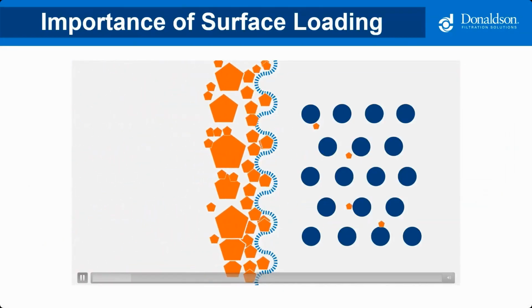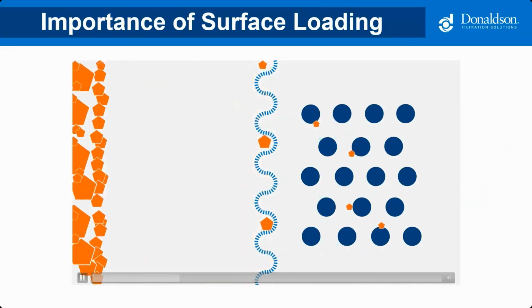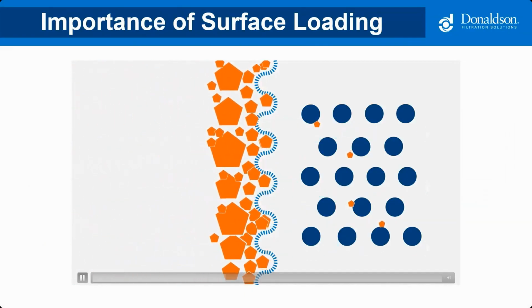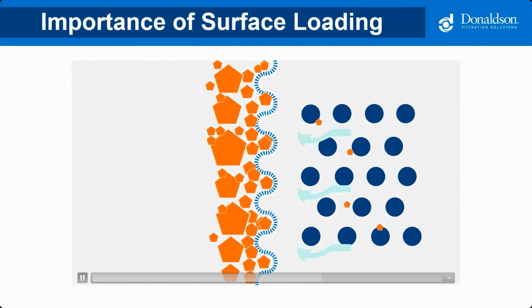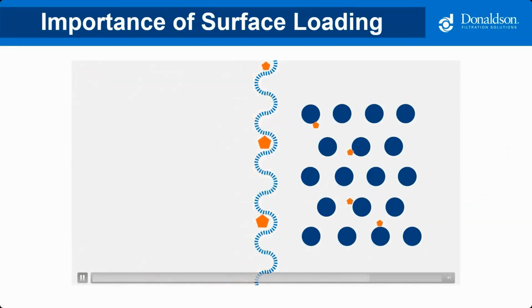You see how those really small particles work their way into the filtration media, but the larger particles stay on the outside on the surface and aren't easily removed. On the non-fine fibers, the more particulate that works its way into the filter, the quicker the filter has to clean. The more it cleans, the faster it has to be replaced.